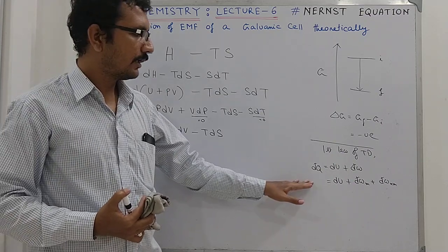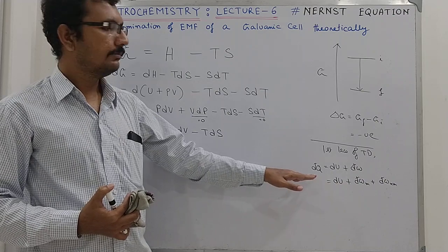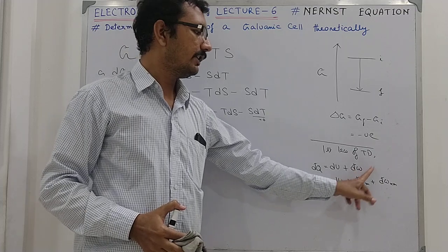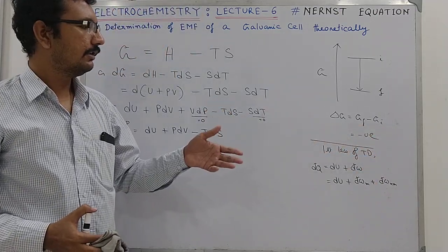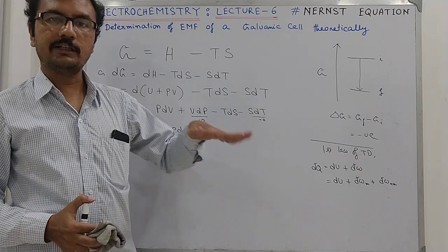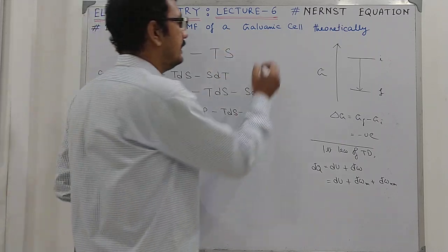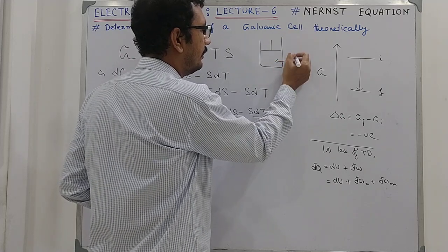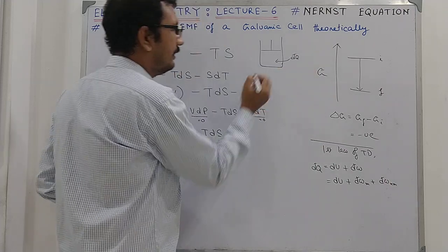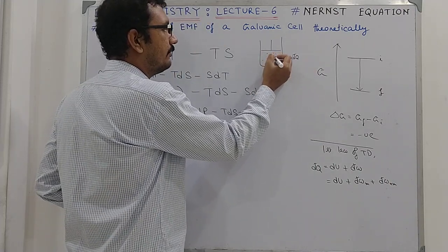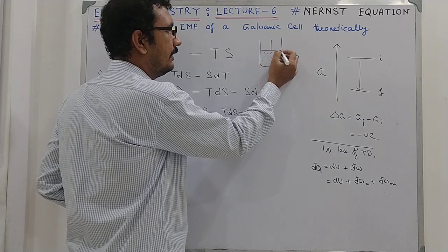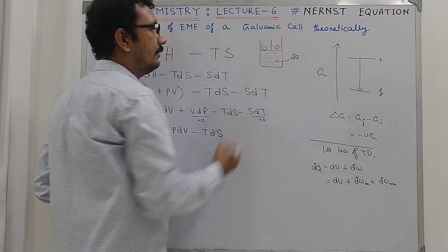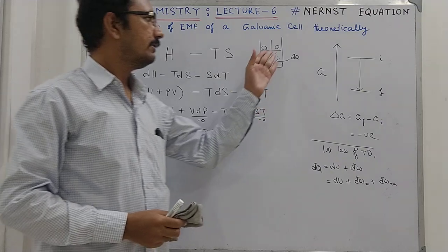Now some of you have not heard of this term. You are actually accustomed to d cross w equals PdV, that is the pressure-volume work. So when there is a direct mass lifting in the surroundings, see this is a gas chamber and you supply thermal energy here, it enters in the form of heat and it increases the randomness of these molecules, temperature increases, internal energy increases and the internal pressure increases and it pulls the piston up along with its mass.